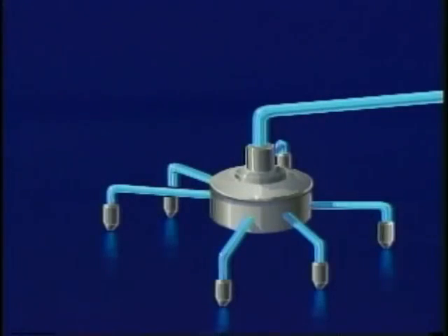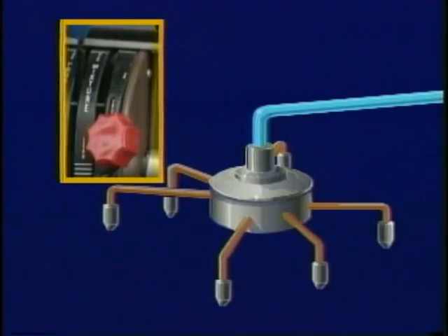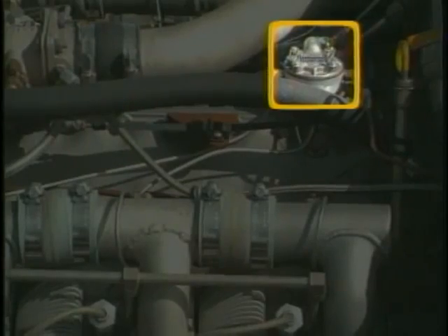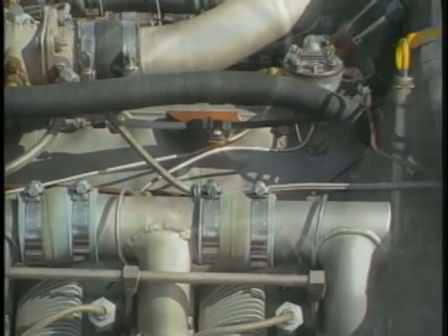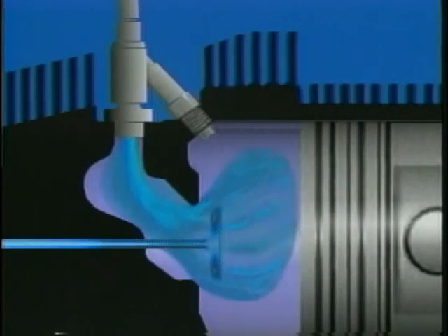Within the divider, there is a set of valves that automatically shuts off the flow of fuel to the engine when the mixture is placed in the idle cutoff position. After the metered fuel leaves the flow divider, it's injected into the engine through the injector nozzles located on each cylinder head. At this point, the fuel is mixed with the air in the induction manifold just outside the intake valves and combustion chamber.